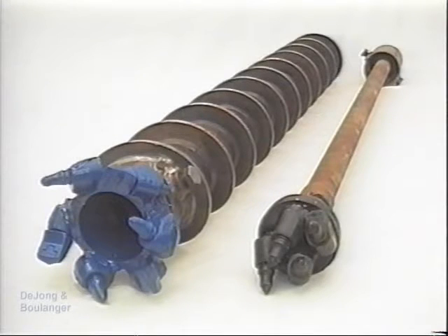The basic hollow stem setup is shown here. The inner bit is connected to drill rods that run through the hollow stem, and the other bit is bolted to the bottom of the lead auger. While drilling, the inner and outer bits rotate together, cutting and loosening the soil at the bottom of the hole. The soil cuttings are carried upwards by the auger flights to the top of the hole.